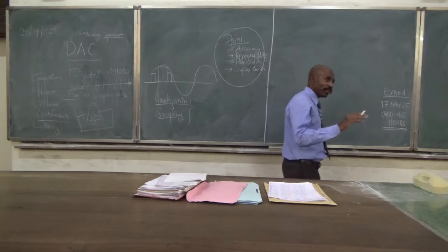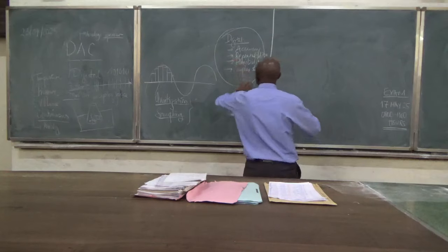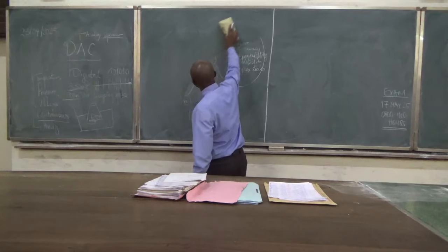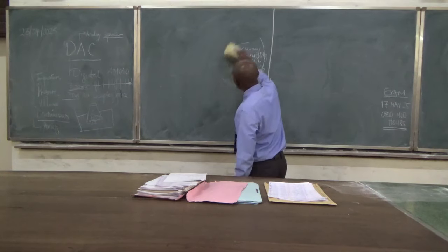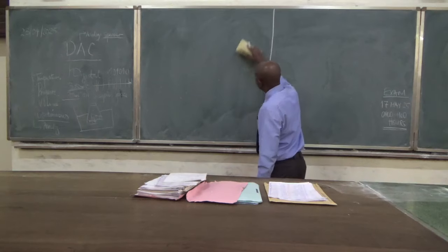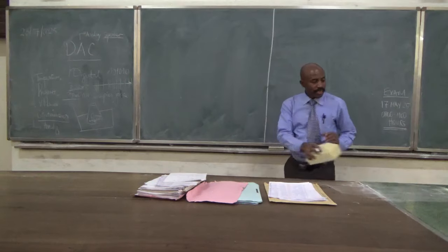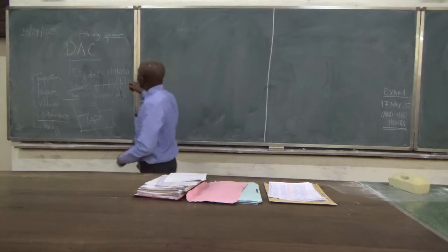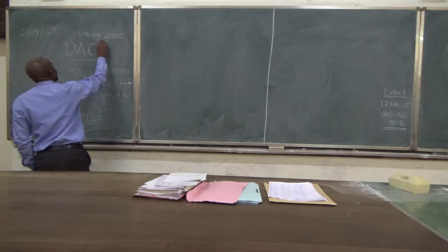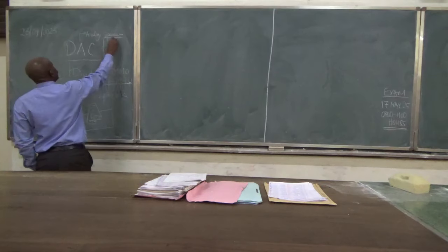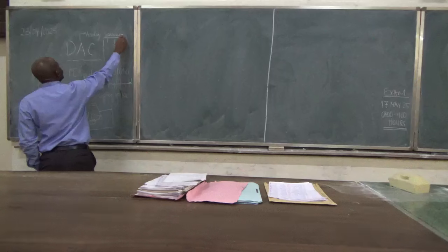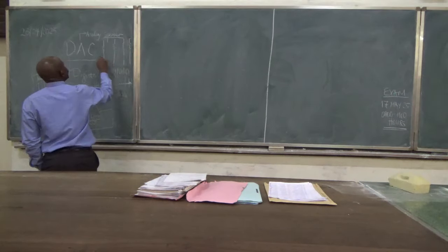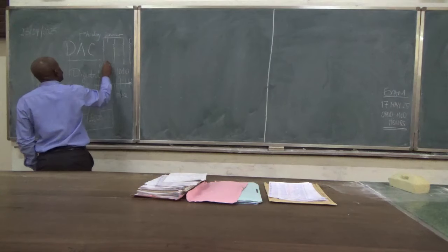So, how far we have gone. Once we know all these things about the conversion, the reason why we convert, then we did the conversion using the weighted method, meaning that we had a bunch of resistances in the form of R, then 2R, then 4R, then 8R, if we are just looking at this being a 4-bit.